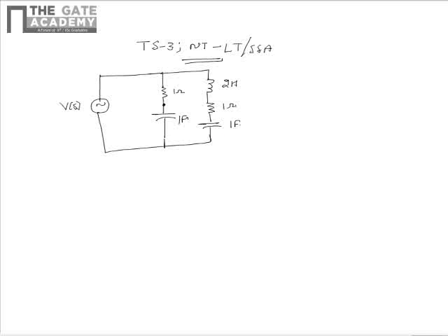The midpoint of 1 ohm resistor and 1 farad capacitor is A, and the point connecting the 1 ohm resistor and 1 farad capacitor in the second branch is B. Please note that this circuit is operating at S is equal to j omega radians per second. It is given that phase of VAB of S divided by V of S is 0 degrees. So from this data we need to find the value of omega at which this condition is satisfied.